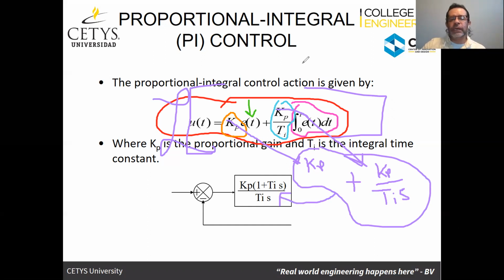What we see here with the integral in that transfer function is that we are adding on the bottom this S that we were looking for to automatically increment the type of system. So whatever type the system was before, after applying the integral controller, the type automatically increases by 1. And we're going to talk a little bit about this term here on top. So we're also adding another term on top, but if we make this small enough, it's something that isn't going to affect the system.